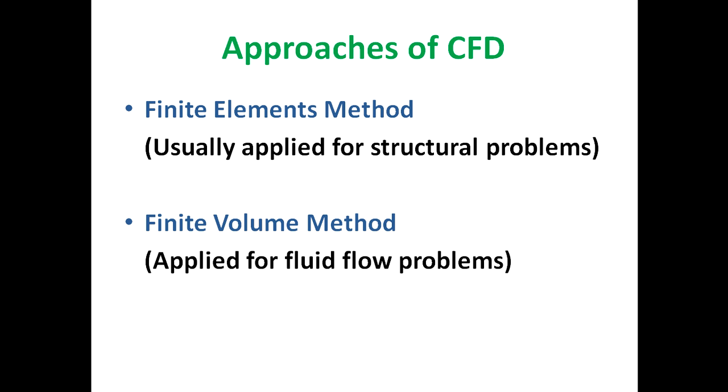In the process of CFD, as I already told, there are different approaches. If we divide it into linear elements, that is called the finite element method. Generally, the finite element method is preferable for structural problems rather than flow dynamics problems, although we can apply it in CFD also. Next is the finite volume method.